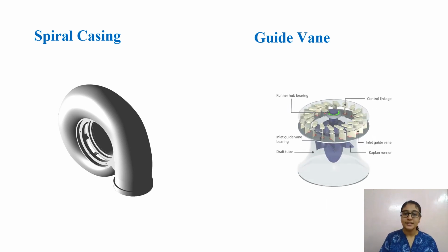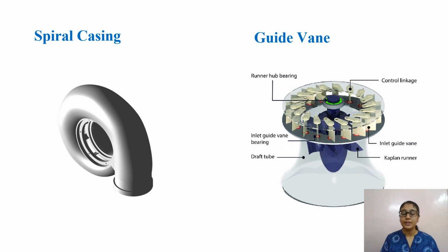Inside the spiral case is a set of vanes called the wicket gates. These control how water flows into the turbine. The wicket gates are controlled by an external governor system. This opens and closes them in response to the conditions on the national grid. A high load on the system slows the turbine, and the governor system reacts by opening the gates further to speed it back up. Conversely, it will narrow the wicket gates in response to the low load on the system.